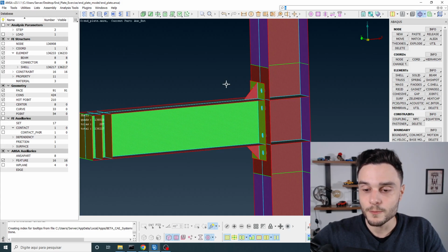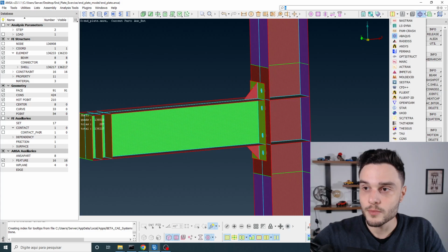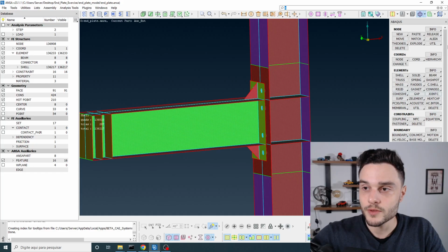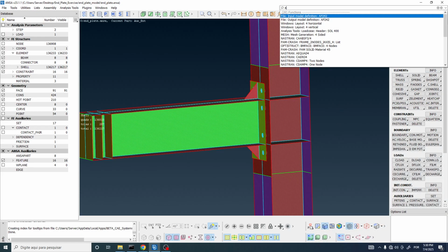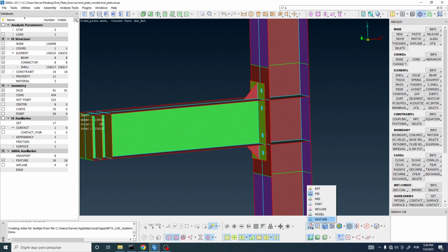So first of all, select from this drop-down list the Abaqus deck, so that you have access to these tools that are related to Abaqus. And in the draw mode, this button here, select PID, so that the visualization of the parts is as per their PID or property ID.